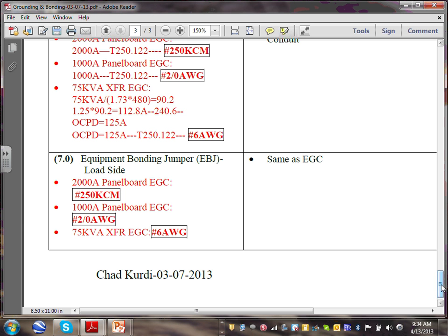And the current is going to take the least resistance path. There are studies, if you read through that book, it says if you have an EMT conduit, especially metallic conduits, actually the majority of the current will go back, surprise, not on the equipment ground conductor. It will go back on the shell of the conduit. So if these are not tight, they will arc and burn.